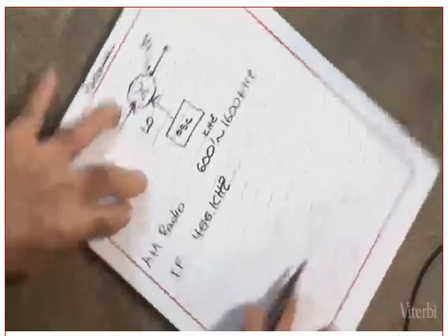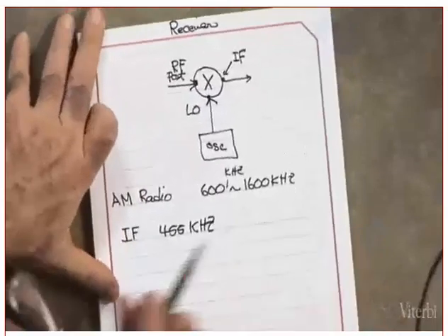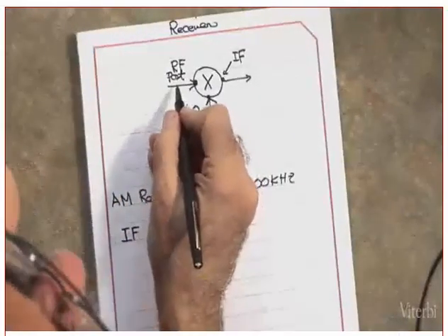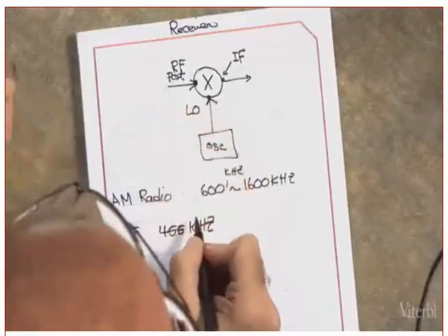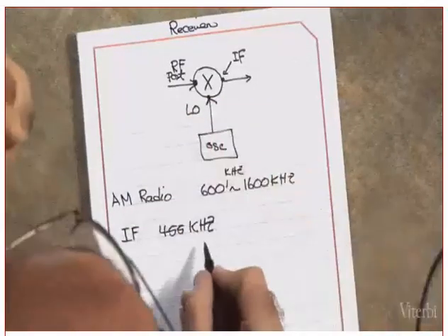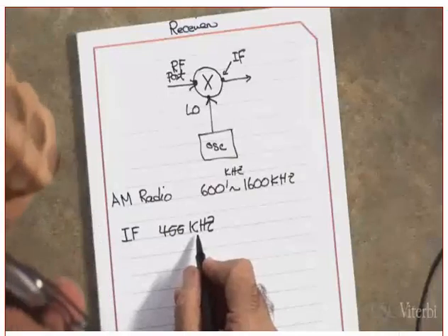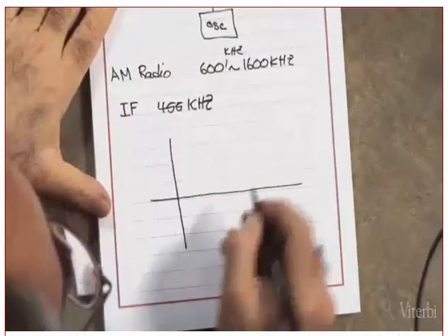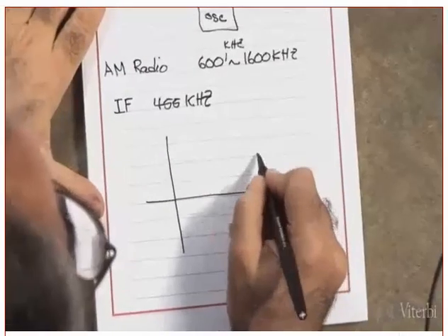We just started. So, I need you to explain to me one thing here. Let's assume, just for the sake of argument, the desired channel is 600K. Yes? What should the local oscillator be? Remember, the IF is 455. In other words, this is what we have. I want you to understand this very carefully. This is the RF.